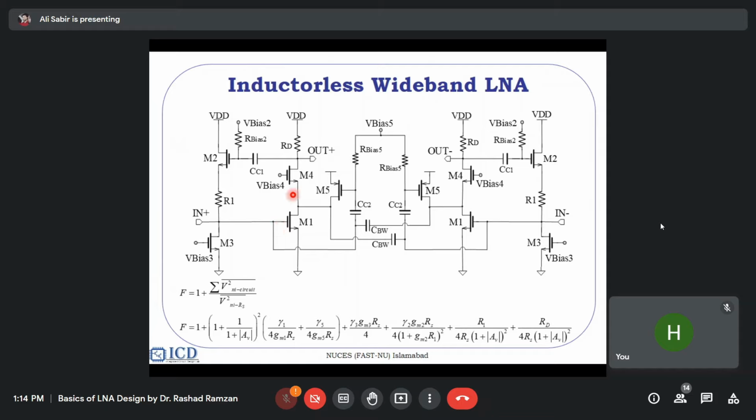Now this design was actually manufactured. This design applies 6 different techniques for the biasing, ternary use, gain boosting, linearity optimization, and noise cancellation in one circuit, and they are optimized close to some global optimum. We don't know it's an optimal design, because even with these 10 transistors, you cannot explore all the permutations.